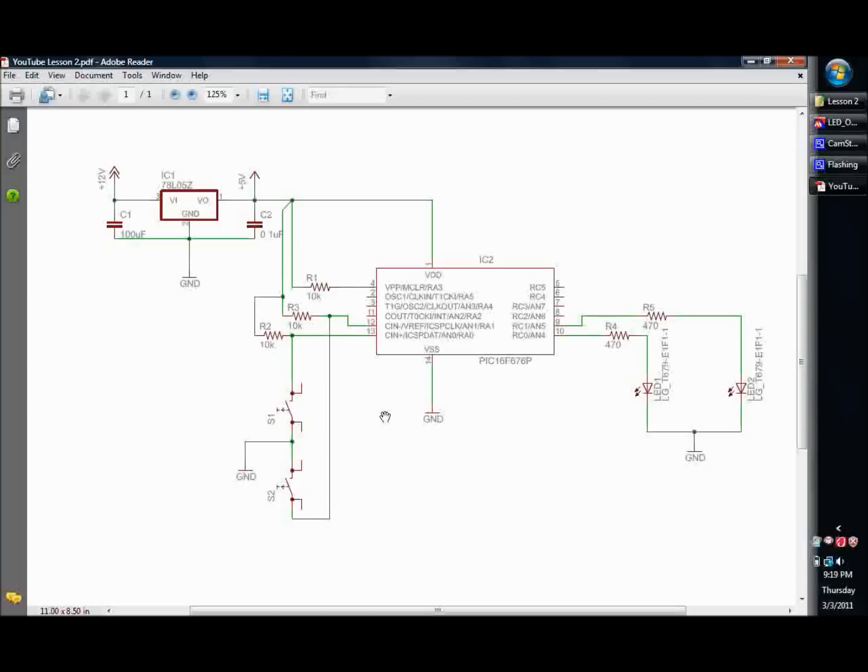But for right now, we'll go ahead and finish up with the simpler stuff, and I'll show you how to use your inputs, and input some data into your system. Right now we'll go over the hardware connections of our system. We've got our 12-volt supply, and we've got our 7805 voltage regulator, and our two capacitors for noise, our 100 microfarad on the input and 0.1 microfarad on the output for noise suppression.